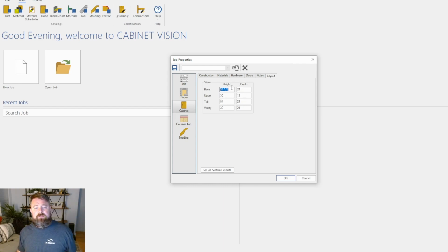This will set some standards, if you will. So like, let's say a kitchen base cabinet height. On average, 34.5 is probably pretty accurate as far as the height of base cabinets throughout the industry. So that's why that's plugged in there. Kitchen cabinets are usually 24 deep. Uppers, 12, pretty standard. Obviously, there are cabinets in between those sizes, and this just kind of gives you a base standard to start out, and then obviously we can edit everything once we're in the room.